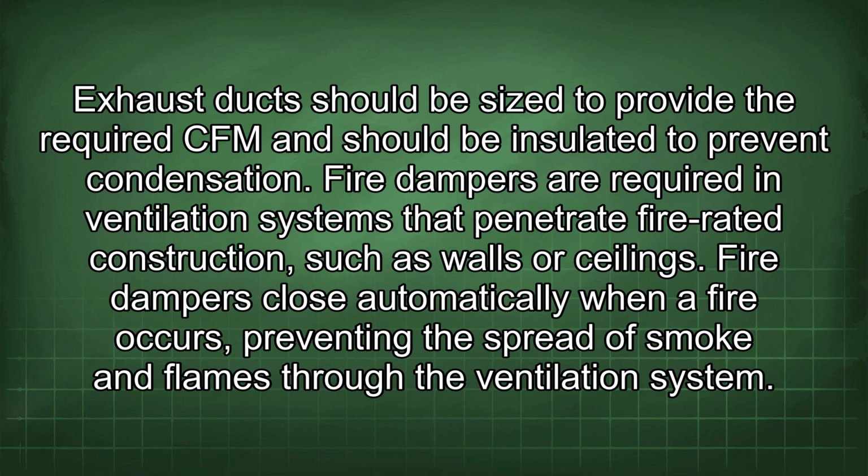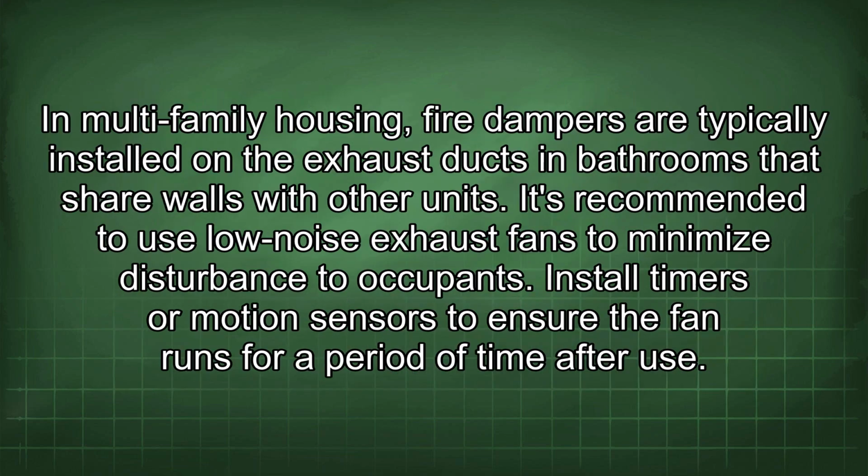Fire dampers are required in ventilation systems that penetrate fire-rated construction, such as walls or ceilings. Fire dampers close automatically when a fire occurs, preventing the spread of smoke and flames through the ventilation system. In multifamily housing, fire dampers are typically installed on the exhaust ducts in bathrooms that share walls with other units.